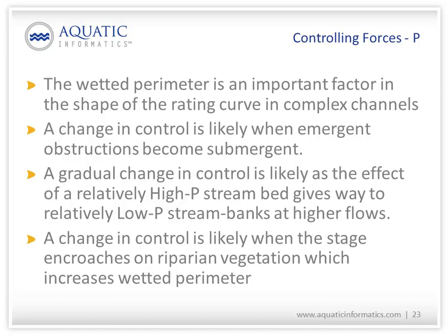And these vegetation effects can be quite dynamic as grass grows up. At low velocities, there may be quite a high wetted perimeter to weeds and grass from the stream bed, but at higher velocities, that grass is going to bend over and lay flat, and it's going to present a much lower wetted perimeter.